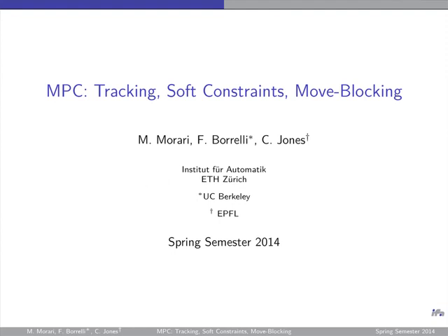The second is soft constraints. Now, what is that? We talked a lot about regions, computing regions, invariant sets, etc. Actually, if the system is open loop stable, and most systems that you work with, fortunately, are open loop stable, and the second thing, if there are no hard state or output constraints, that means strict bounds, most of those regions don't exist. It's all infinite.